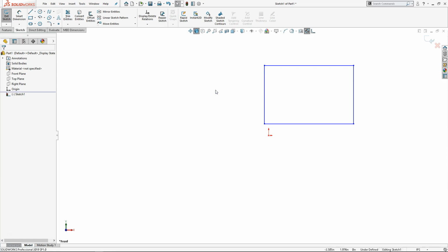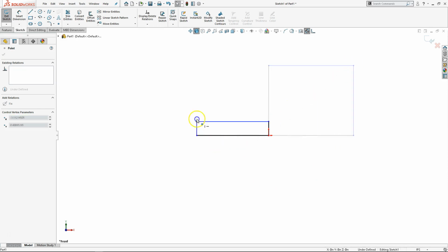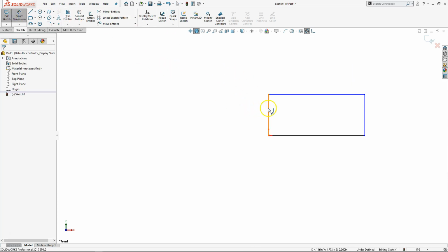All right, so if you are not in the habit of attaching some portion of your sketch to the origin, that would be a very high recommendation that any corner, any point can be attached, and it will jump. You will see that little yellow box. That little yellow box gets you to a coincident relation that now the two lines that are in black are defined. And then what is left is I can rubber band, and that's what I mean by if it can move, it probably will. So at this stage, we can put in dimensions.